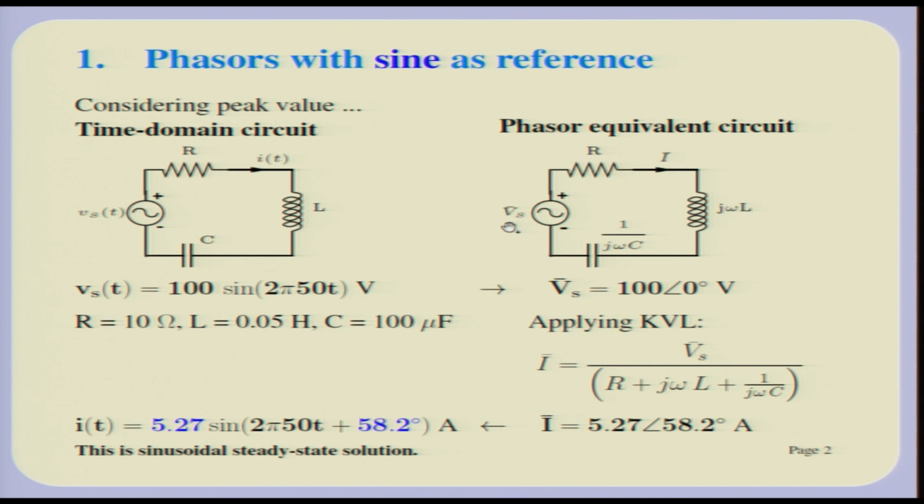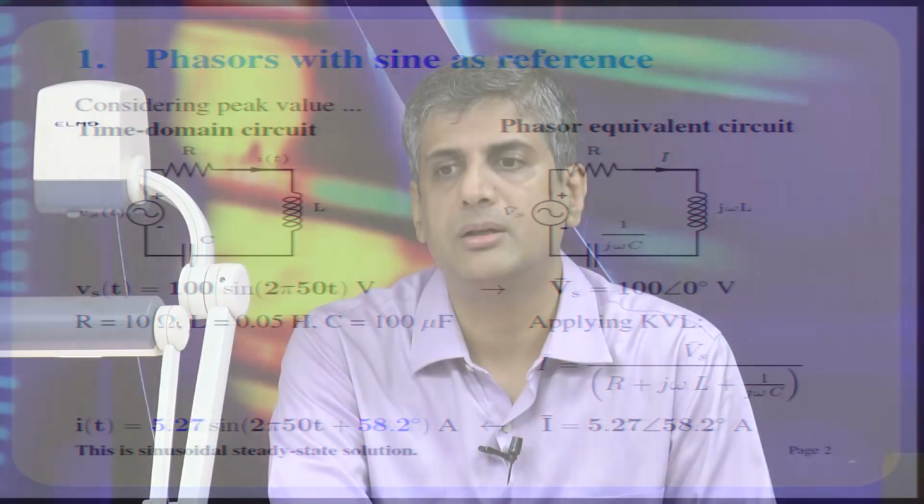Okay. So, of course, finally what we need to do is solve this circuit. So, a simple way of applying Kirchhoff voltage law, we have done this before in a sense, because we have tried to look at it more generally for e raised to st plus alpha, but you can of course use the same analysis for e raised to j omega t, for DC inputs with s equal to 0, or you can also get sines and cosines, because sines and cosines are in fact combinations of e raised to j omega t and e raised to minus j omega t.